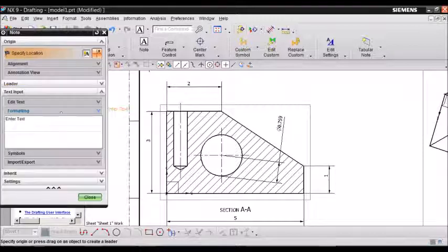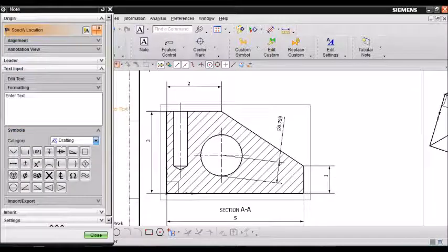and click here, so you can have the whole access to the menu. In this case, we're going to use symbols. Symbols are really important because you can add, for example, a diameter, a depth, or a plus minus for tolerance. So you can create these things by yourself. In this case, the diameter of the hole is 0.5 with the depth of 2.